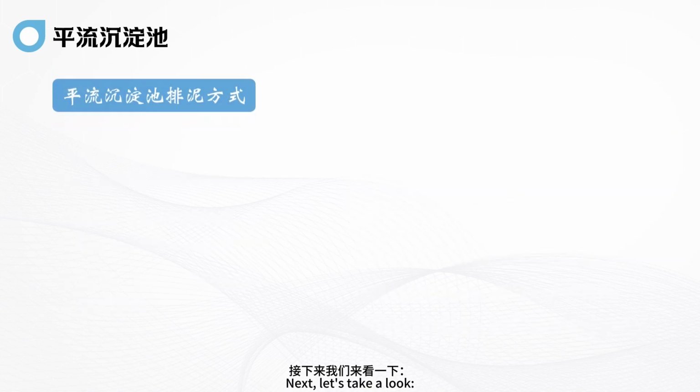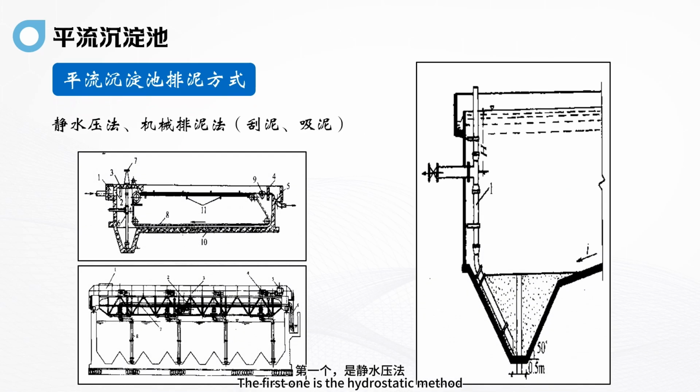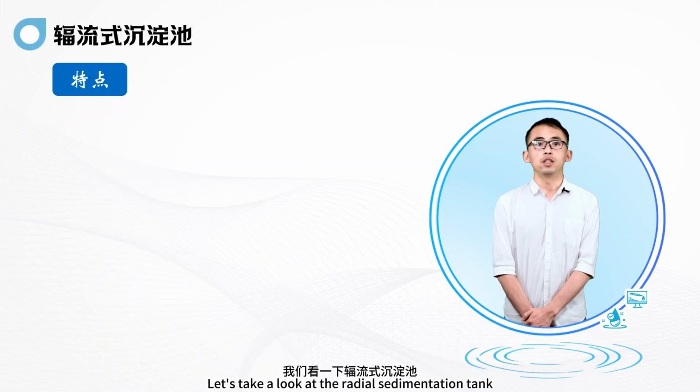Next, let's take a look at the sludge discharge methods of the horizontal flow sedimentation tank. The first one is the hydrostatic method: through water flow and static pressure, directly controlling the pressure, the sludge that has settled into the mud hopper is discharged. The second is the mechanical sludge discharge method, using a mud scraper or a suction pump to directly scrape or suck away the sludge. These are commonly used sludge discharge methods of the horizontal flow sedimentation tank.